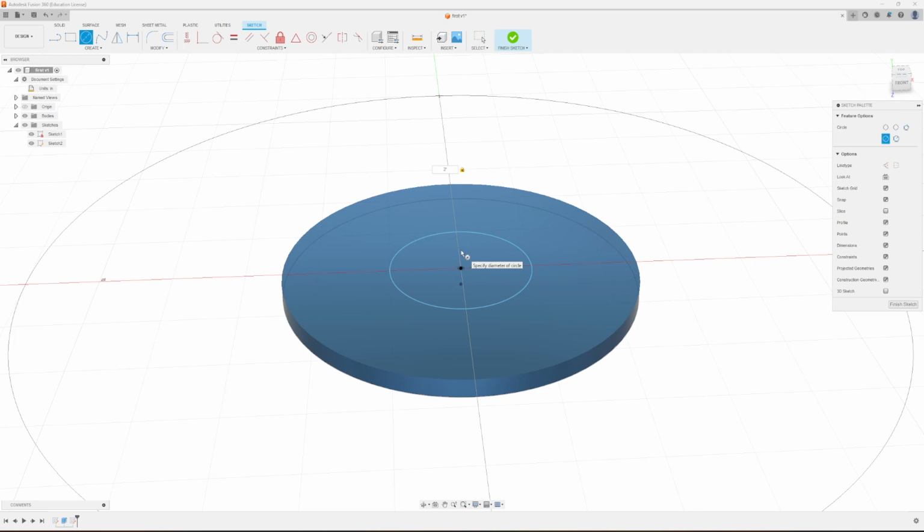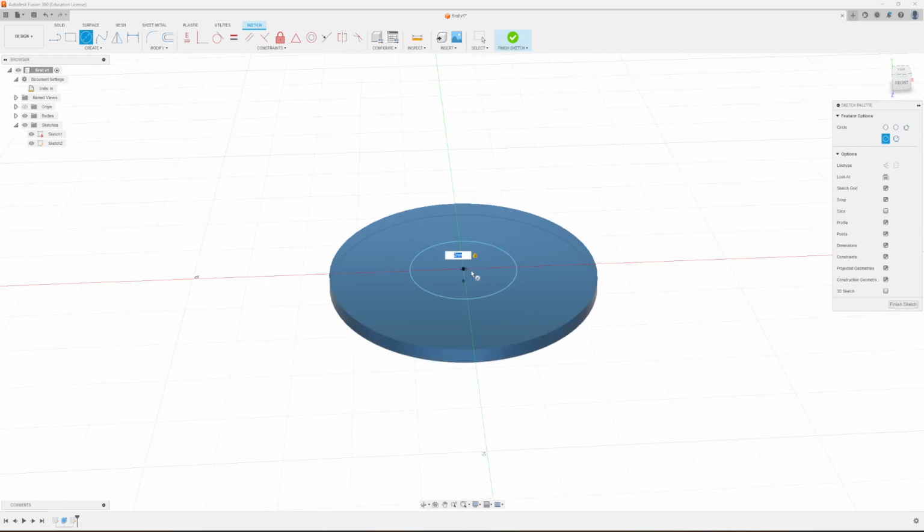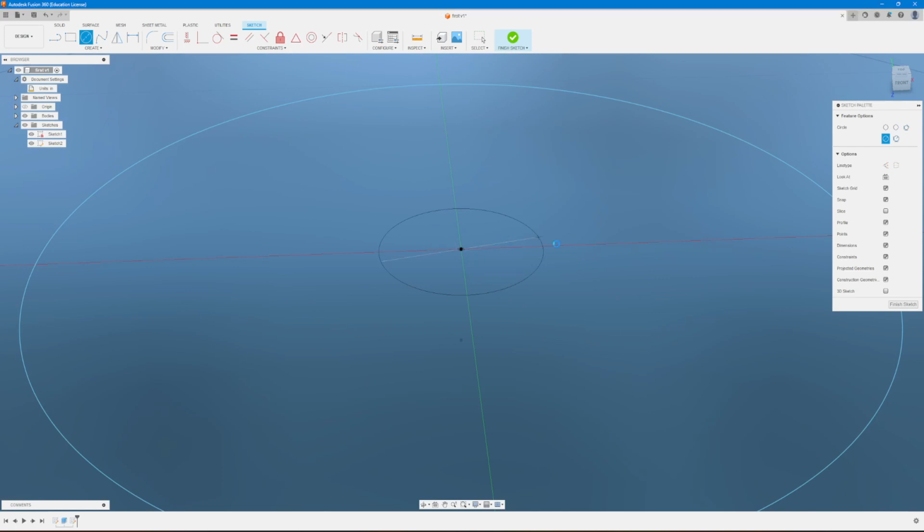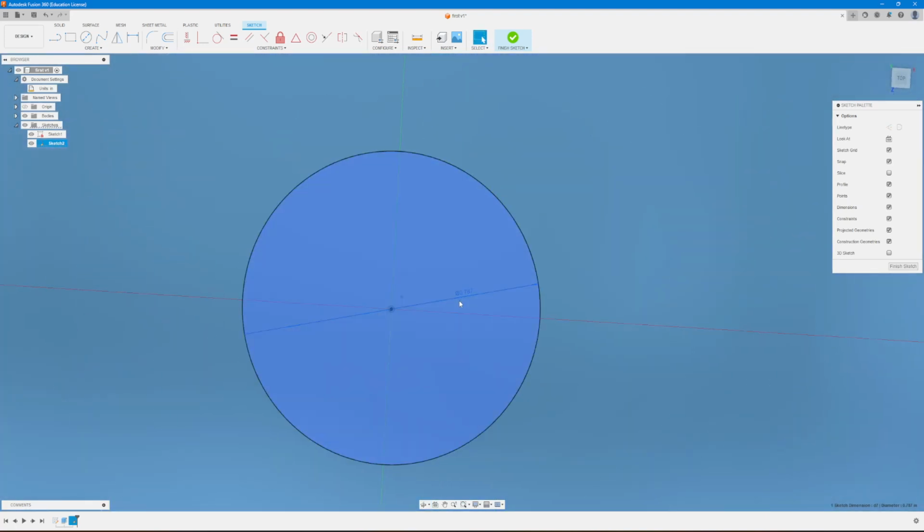Not a comma. Excuse me. I could hit this and it goes to feet, and if you shift to it, it goes to inches, which is its default. Or I can just type in millimeters and it will do 2 millimeters. So you can change this at any time. You can also do centimeters if you want to. It will change, and whenever you actually add it, it will add it as centimeters, but it will show it as inches. So that is rounded up as centimeters.